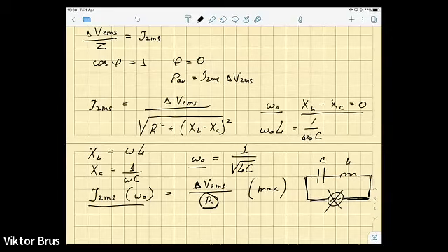At some different frequency, this power supply in this given electrical circuit can operate without any problems, because there is a discrepancy between values of inductive and capacitive reactance. But at the specific frequency, which is the resonant frequency, this circuit is under high chance of being damaged if we don't have a large enough active resistance included in this circuit. So that should definitely be taken into account.